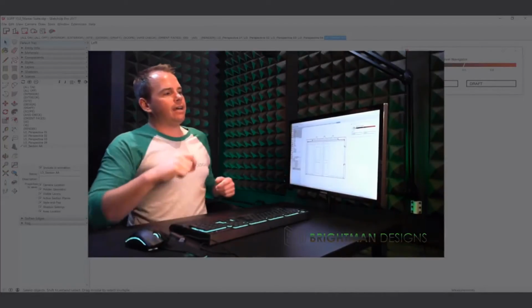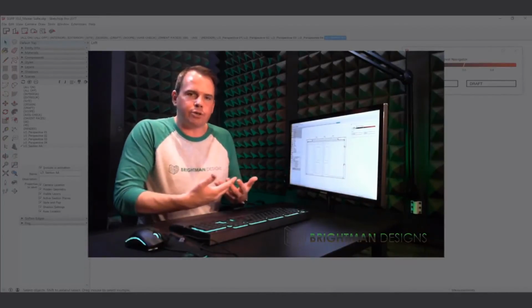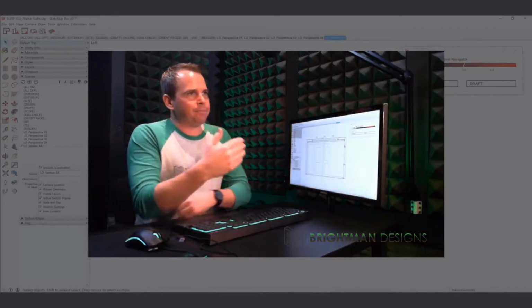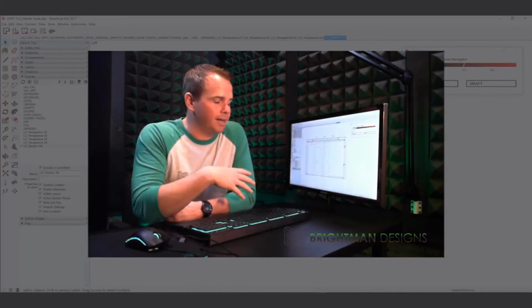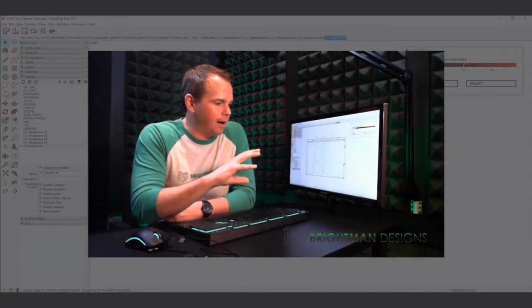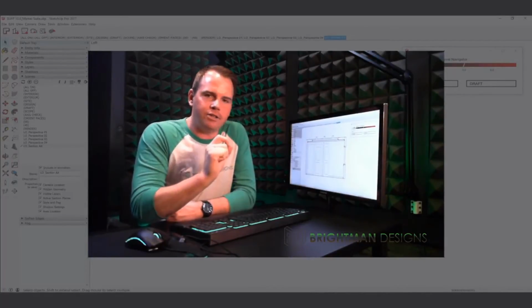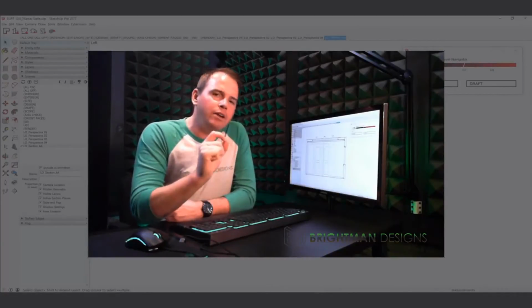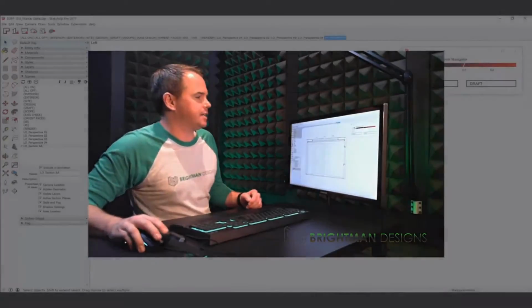You should use layers to control that visibility permanently. Now, it's not to say that you can't hide something and have that hidden geometry saved, but this is where I'm going to demonstrate this, and maybe this is not the case anymore, but this has been my approach forever: you use layers to control visibility. Hiding is a utility. If you hide within a group, it doesn't hold on to that. All right, so let's test it.